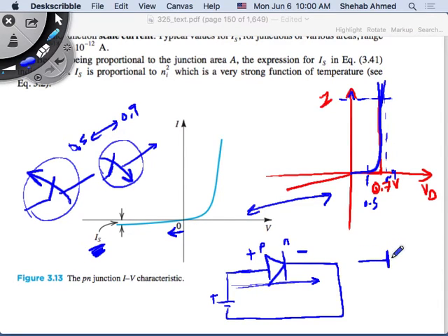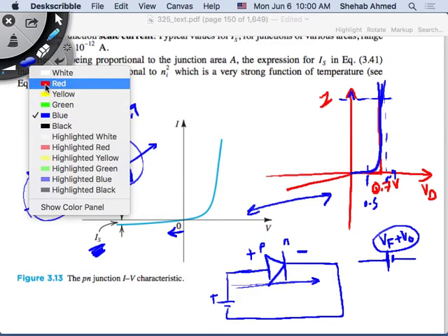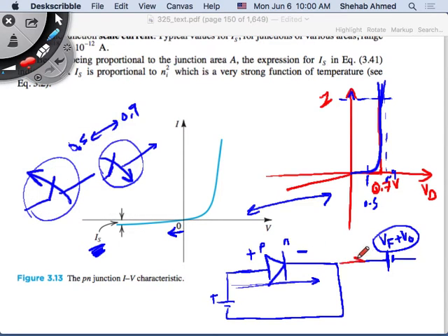Actually, there's a voltage here. This is my new barrier voltage VF plus V naught. This is a voltage, right? That's opposing your current. Current is flowing in this direction. This is the current flowing here. This current is flowing, and it will only flow if the voltage is greater than this voltage, right?